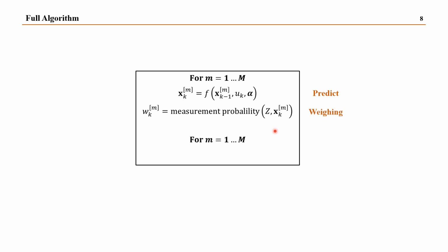And now we go to the final step, which we call the resampling. Again, we go through all the number of particles. What we do is that now we have the weights, so we redraw the particles with probabilities related to these weights. So now we kind of have a discrete distribution made of the weights, from 1 to m, and we just sample in proportion to those weights.